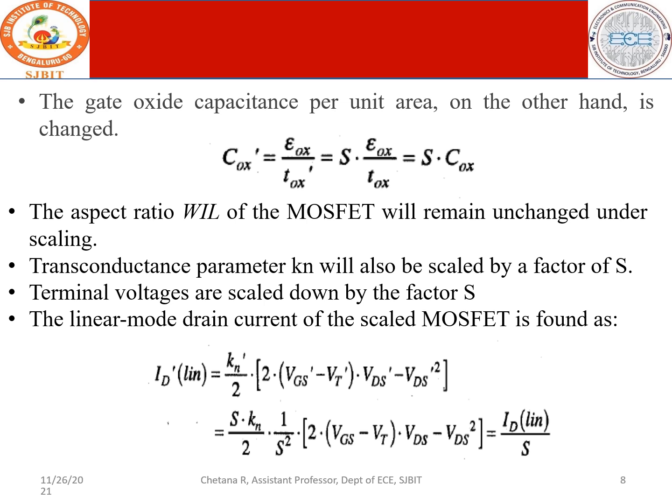Next we have a parameter called gate oxide. Right now we are familiar with this term gate oxide, which is below the gate layer, and normally it is thin ox. The gate oxide capacitance is the capacitance existing within the gate oxide per unit area, given by this formula. We know capacitance C is equal to epsilon by D. Epsilon is the permittivity, D is the spacing between two parallel plates. But here we are considering the capacitance of an oxide, so it is given as Cox.